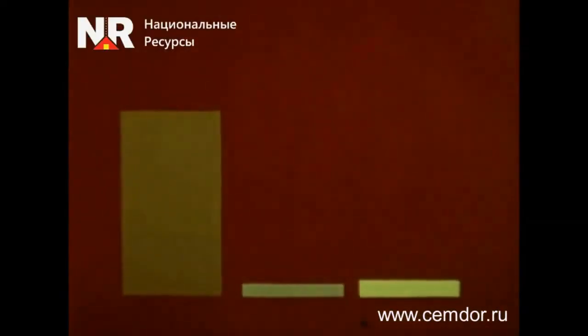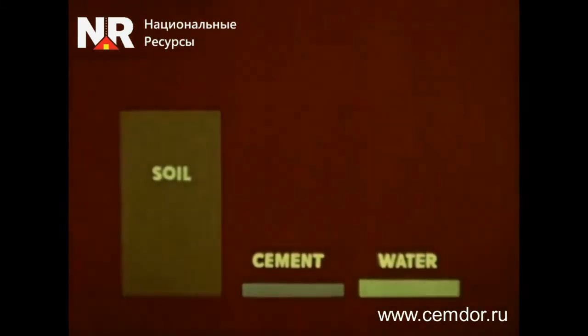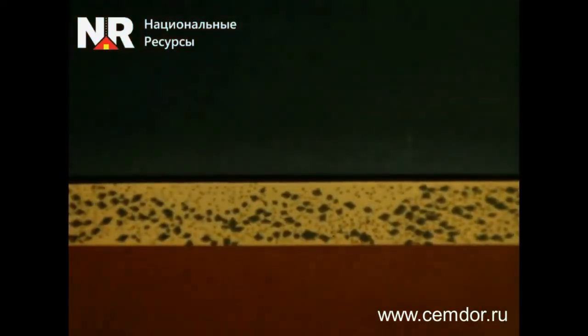Soil concrete consists of soil, which makes up at least 95% of the total mass, and Portland cement. The amount of Portland cement depends on the design characteristics of the road section and the stabilizing additive used. Water is necessary for the hydration of the cement in the mixture as well as to achieve maximum soil compaction. When mixed, the soil, cement and water form a dense paste-like mixture ready for constructing the structural layer and its compaction. After that, the resulting mixture hardens, gains strength and does not come out of the mold, and it turns into soil concrete, which is resistant to moisture.